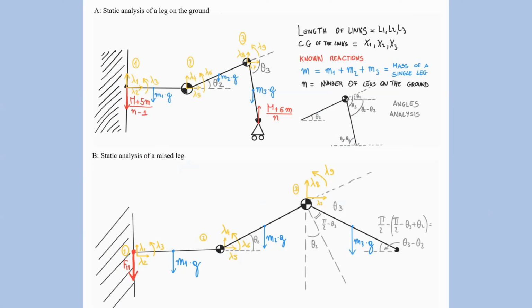The study of the statics of the robot legs was performed in order to obtain the values of the torques to correctly apply in the joints, and to verify that the chosen electrical motors can provide such torques. It is assumed that the only external force acting on the end effector is gravity force, and that the mass is equally distributed in the body, so that a one-leg study can be performed.